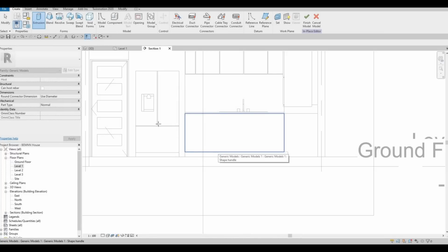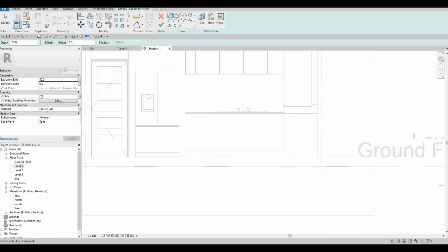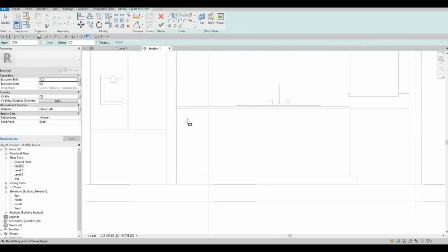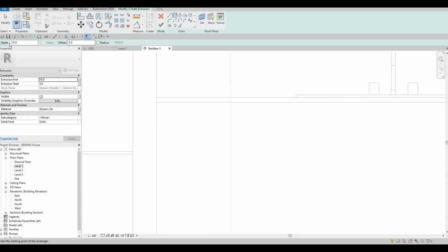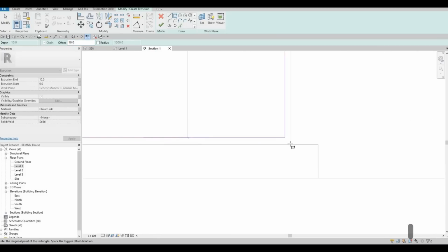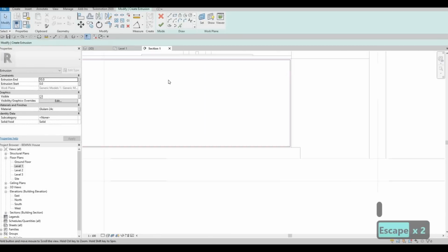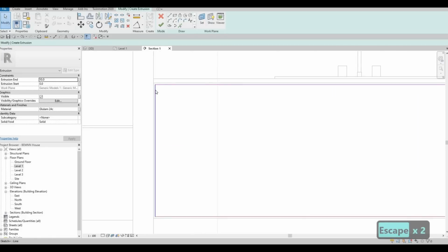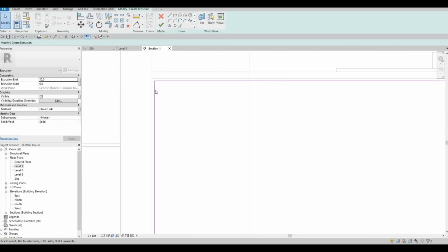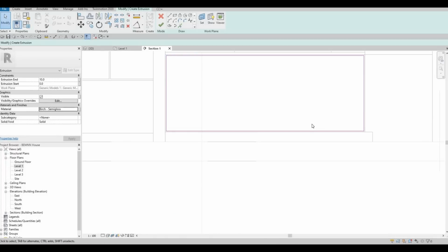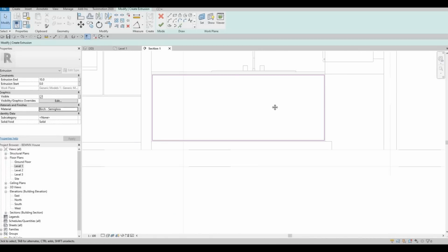This is a very important part, and then click on rectangle. We need to offset this to 10, and then same corner, spacebar, and then corner again. The spacebar is just to change from the inside to the outside, or outside to the inside. Here Douglas fir, or sorry, birch semi-gloss, same material as the base case.